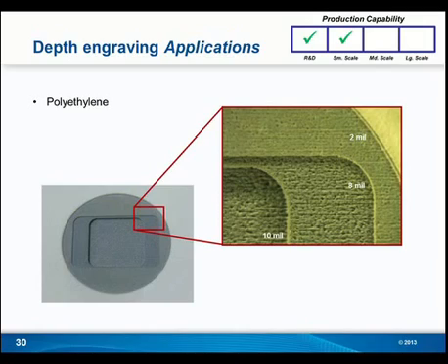And we've seen that with different materials, your control can be extremely advanced. When removing an epoxy substrate over a circuitry that maybe has wire bonding, we've actually been able to remove high sol epoxy in as little as 5 to 10 passes. Or thermoset resin over the top of a metal, and we remove that in maybe 2 passes, but it's 20 mils thick, so maybe 10 mils per pass or 1 mil. And then we've even dialed it in where metallization removal on a substrate can be done where approximately 1 micron of copper is removed from an actual circuit board substrate. So incredibly accurate.